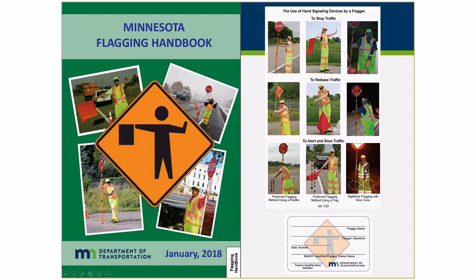Before, we just had a couple of these situations out there. It was just the flag and the paddle. There are situations where you can use a flashlight with a red glow cone, and this shows you how to control traffic through these pictures. Plus, there is a Flagger Train the Trainer certification card that is in the field manual. It's in the flagging handbook. This can be filled out to show that a flagger has been trained appropriately.